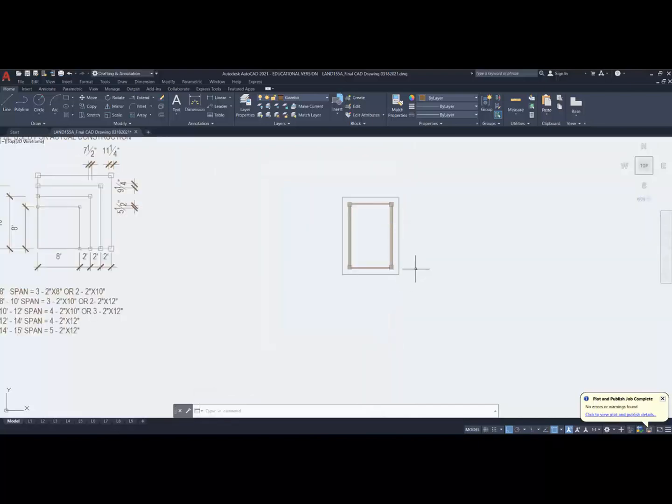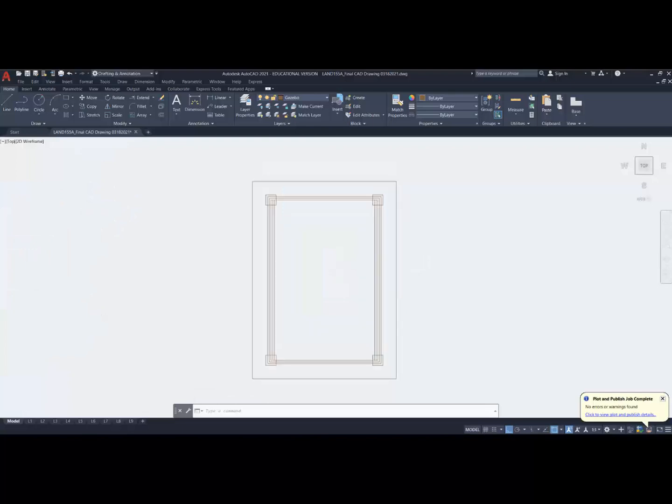But this is good. This is going to be the top of my gazebo, and I'm using this as an overall thing. I'm looking at the structure, I'm looking at the shapes of everything, and now I've got to draw the actual roof itself on top of this. So I'm using this to draw everything at once, and then afterwards I'm going to remove or create hidden lines to define all the other elements. So to draw the roof, we actually draw 45-degree angle lines from the 4 corners.